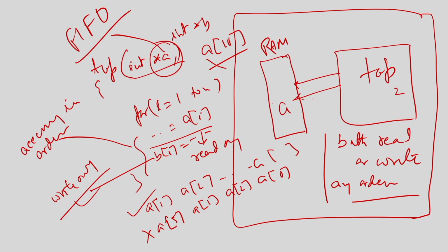It will create address, data, the write enable, the read enable and all those things, and then it will just give some address. If you want to write, it will make the write enable active, or if you want to read, it will just make sure that it is not write enable.